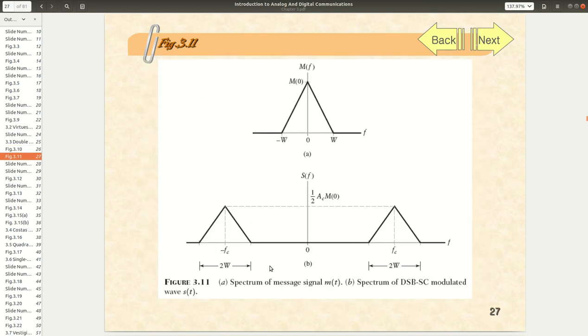Now in the frequency spectrum, you see this is the signal m(t) and M(f) here, of course, and here after the modulation you see two components at fc. However, if you remember, you don't see here the delta function for the carrier wave.